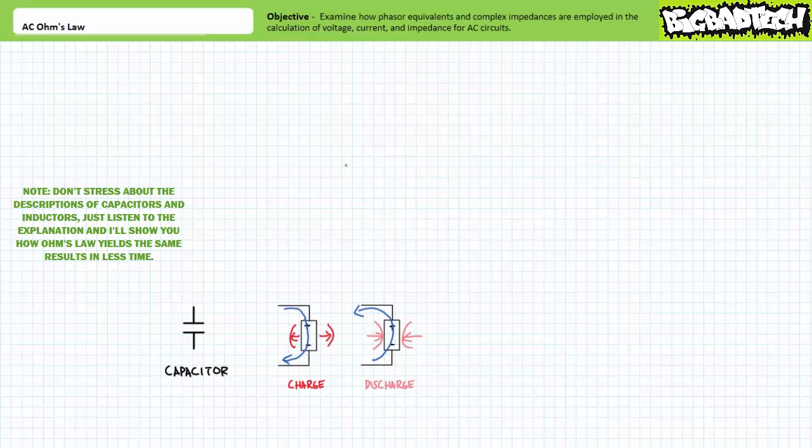The other half of a sinusoidal cycle would be a repeat of the previous process, only polarity is swapped. During the charging process, current would flow into the capacitor bottom to top, and an increasing voltage differential would develop across the capacitor, positive to negative, bottom to top. Again, in this sense, the capacitor is acting just like a passive element, absorbing energy.